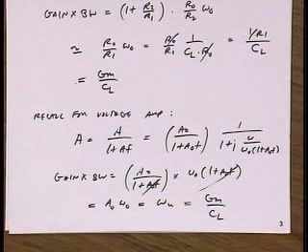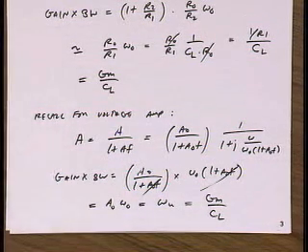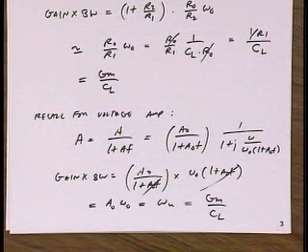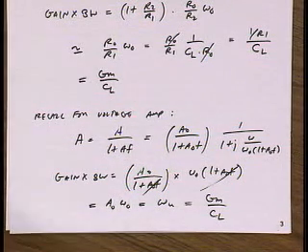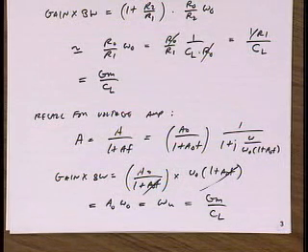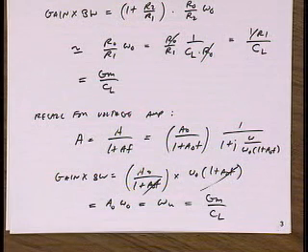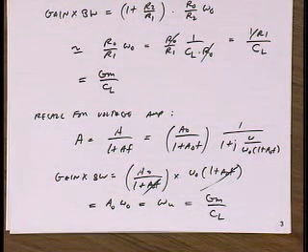Let's say I fix the power consumption of my amplifier. And I say for a given fixed power consumption, which topology is going to give me bigger gain bandwidth product? I would think they're about the same because R1 gets compared with 1 over GM as well, because the impedance of that node is about 1 over GM, so they're ordered the same.